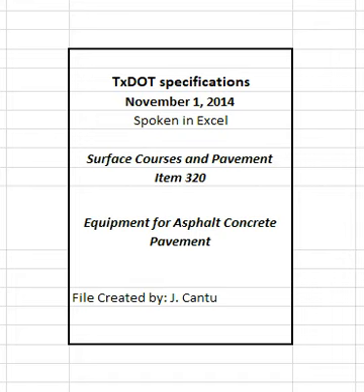Furnish a sampling port on the line between the storage tank and mixer. Supply an additional sampling port between any additive blending device and mixer. Supply an inline viscosity measuring device located between the blending unit and the mixing drum when AR binder is specified. Provide a means to calibrate the meter on site when an asphalt mass flow meter is used.